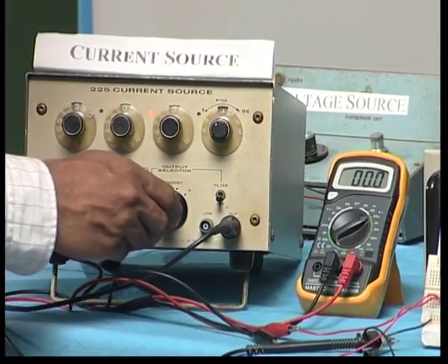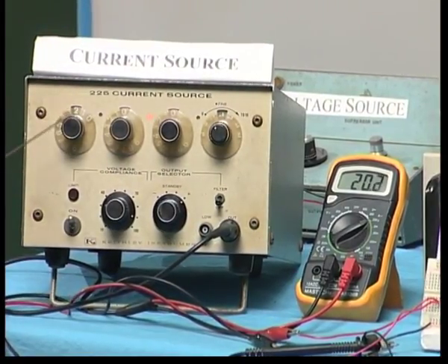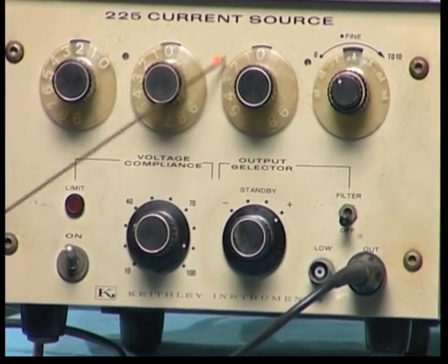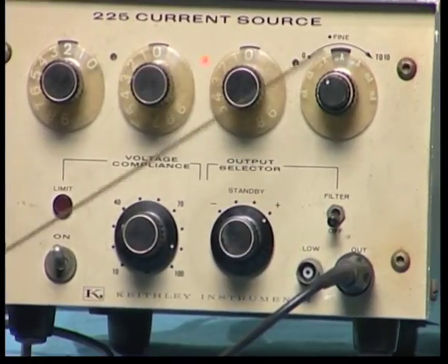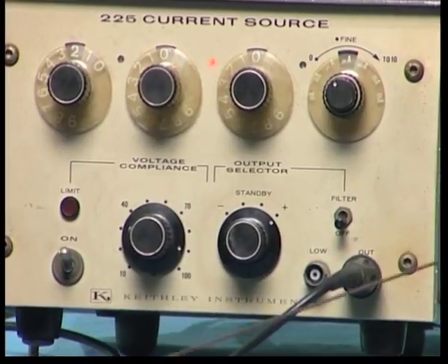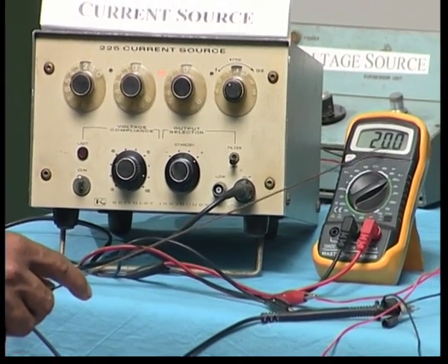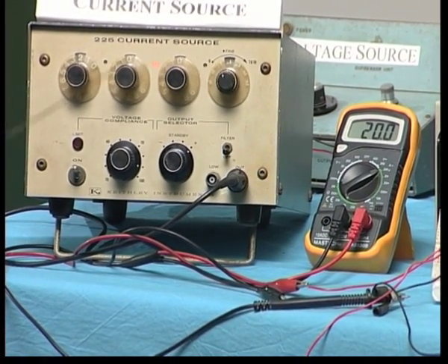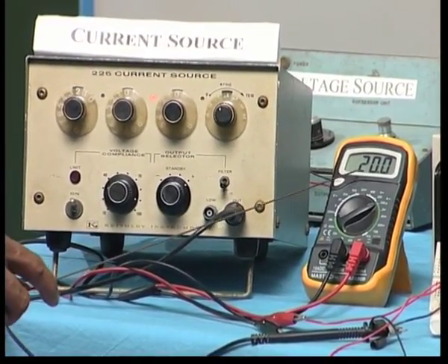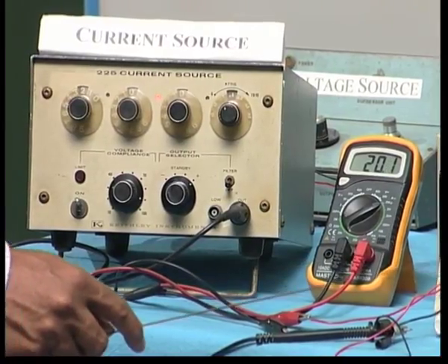Now, let us try to apply the current. I do not know whether you are able to see the dial, it is 2 here, it is 0 here, and this is the decimal point, and therefore 20 point, that is microamperes. So, it is 20 microamperes, and that is the current, and you can see here it is in the 200 microamperes range, and it reads 20 microamperes. 20 is the reading here. So, this and this are perfectly matching. You are applying 20 microamperes and you are also reading 20 microamperes in the multimeter, and that is being applied here. You have a 10K resistor.